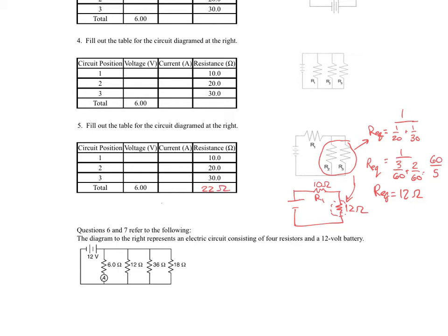All right, from there you can use Ohm's law, V equals IR, and solve for that total current coming out of the battery. If back in our drawing, that would be the total amount coming out here, which is also going to be how much flows across this R1. We'll call it I1, but it's really the same as the I total.